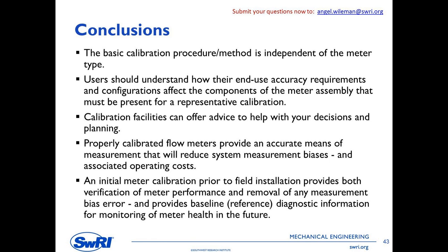Calibrating the meter before you install it, even if that meter is only off by 0.1%, you didn't know that unless you calibrated the meter. So it's a good verification of proper behavior of the meter before you install it in the field. If you don't calibrate the meter and you have a problem, that's going to be one of the first places you look and you say, what's wrong with that meter? Well, I didn't calibrate it, so I don't really know.